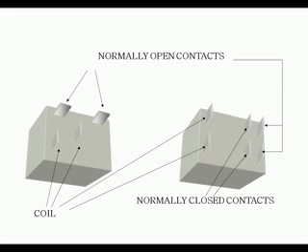The relay has a magnetic coil to open or close one or more sets of contacts. The relays are not repaired. They were replaced on failure. They're used for light-duty applications, and they can be used as a pilot-duty relay. In other words, one relay controlling another. The relay contacts must be able to handle the amperage draw of the load being controlled.